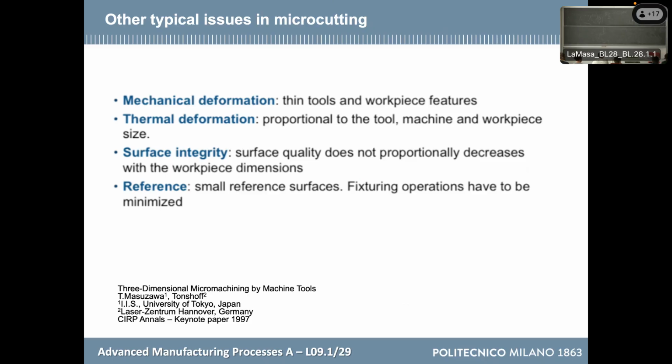So you see, this is nice because you see how the geometry of a part is made on aluminum, because they tell me that in space they prefer to have aluminum instead of silicon, because silicon is fragile. And this part is small, but not too small. It is some millimeters. And a piece of silicon of some millimeters is too fragile, right? Do you know why it is too fragile? This is somehow connected also to the behavior of the mills. If you have a thick piece of a fragile component, why do you risk more to break it with respect to when it is fine, it is thin?